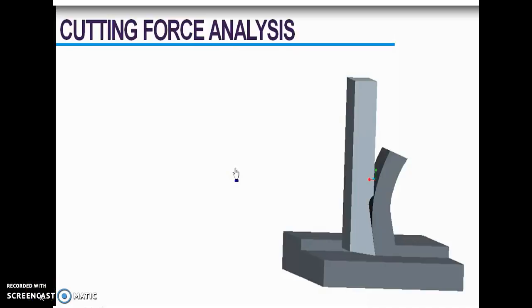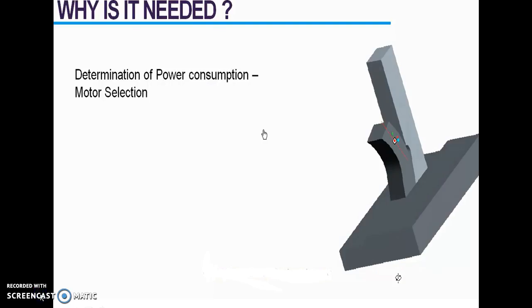Hello. Now welcome to the next lecture for this session, that is the cutting force analysis. Now why is this cutting force analysis necessary? The first point is the determination of power consumption. While designing any machine, we require a motor selection, and for that purpose we require the power consumption. Power consumption is determined by using the forces acting on the machine